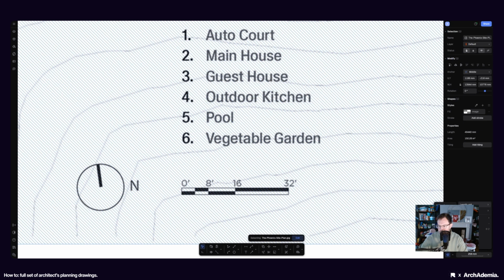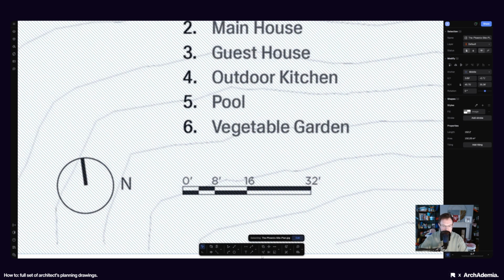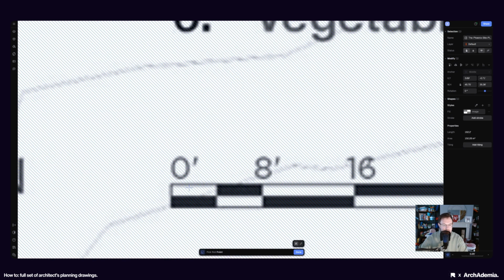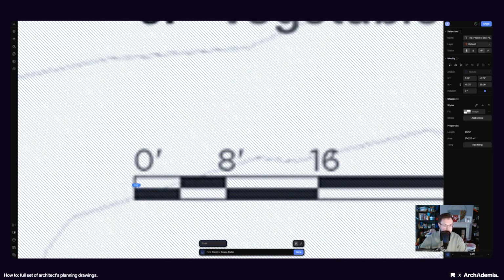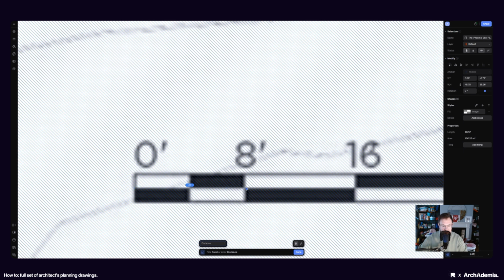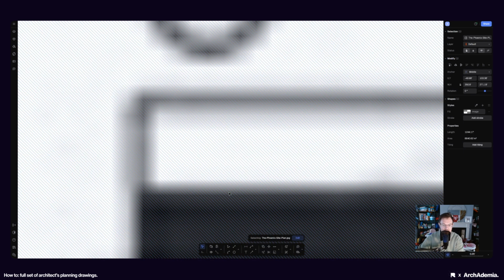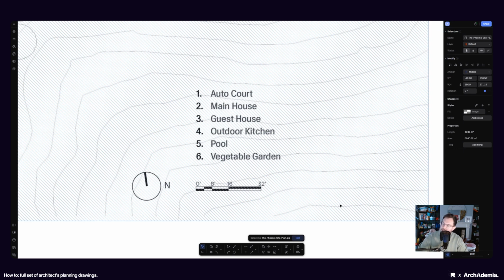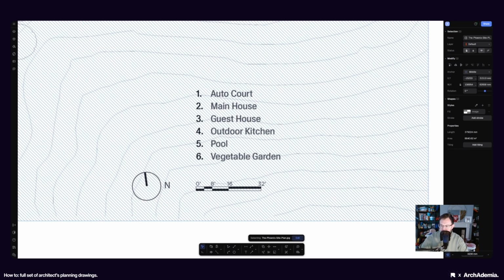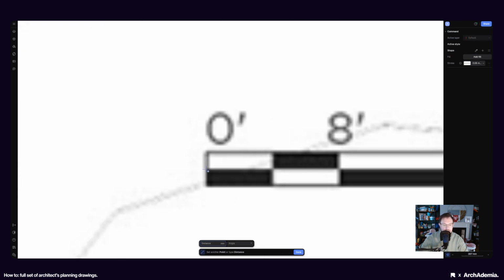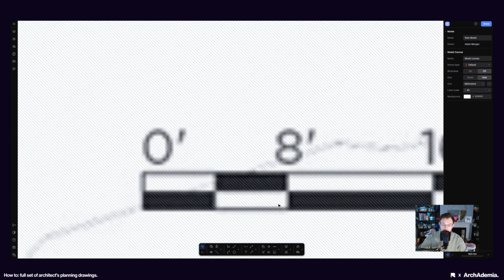I wonder whether, if we go length, feet for now, and then go scale down here, it uses a 3-point system. So you click the first, you click the second, and if I then go 8 feet, I think that's about 2.5 meters. If I go millimeter now and go back to that, there we are. That's good. I actually didn't have that one prepared. Alternatively, just use an online converter. Just Google 8 feet in millimeters. But I know that is about right.